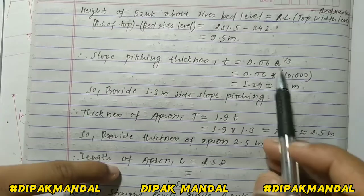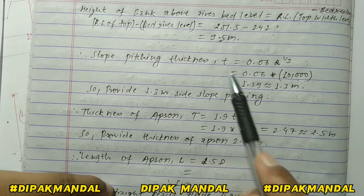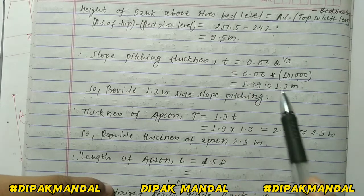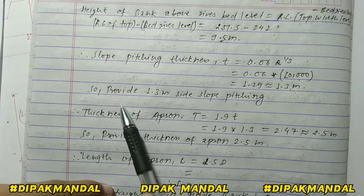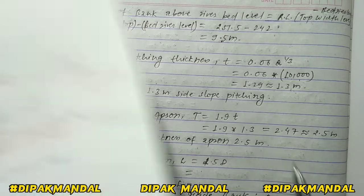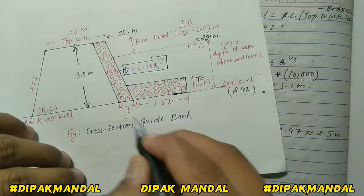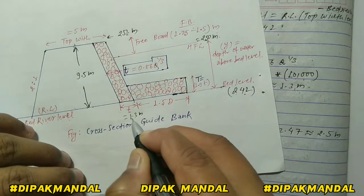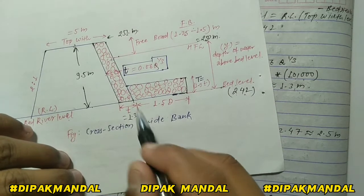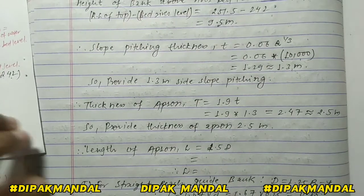So for this we use discharge equal to 10,000 and the slope pitching thickness, that is the value of small t, becomes 1.3 meter. So we have to provide 1.3 meter side sloping pitching. Okay, so this thickness t equal to 1.3 meter. Okay, so you have to show this value in figure.